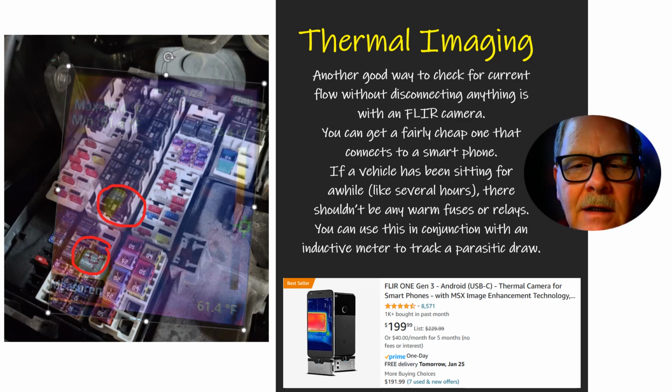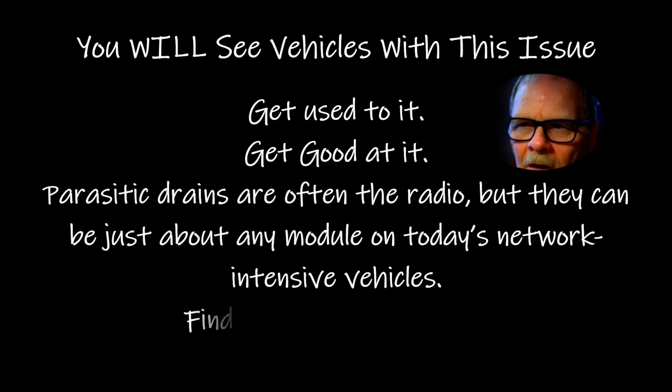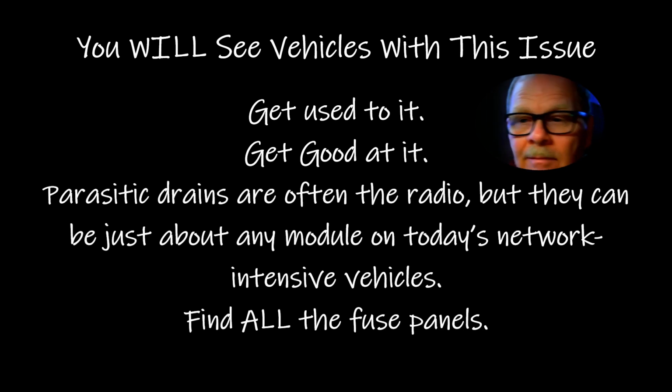So just be aware of the fact that you don't want to get a false positive and go off in the wrong direction. You're basically going to need to gather a library of skills by chasing a lot of parasitic drains, and you'll get better at it. You're going to see vehicles with this issue if you work on cars. Get used to it, get good at it. Parasitic drains are often the radio. I don't know how many times I've seen bad radios cause this.